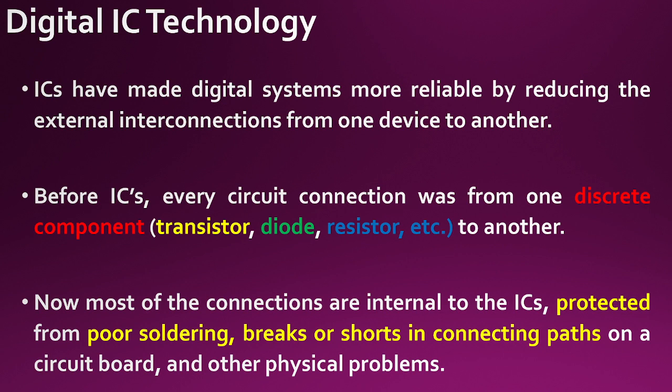Most of the PCBs that we used earlier suffered from a lot of problems like dry soldering. A crack could develop in the bus systems on the PCB, and it used to create a lot of problems once the PCB got older.